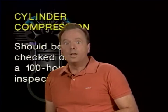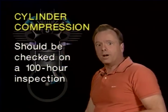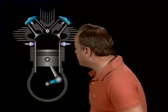And the answer is, on a 100-hour inspection at least, you must check cylinder compression, maybe more often if you think you have a problem. You say, all right, let's assume you're pulling a propeller through and you hear a hissing sound from the exhaust stacks. What does that mean? Well, if you hear a hissing sound from the exhaust stacks, that probably indicates exhaust valve blow-by.